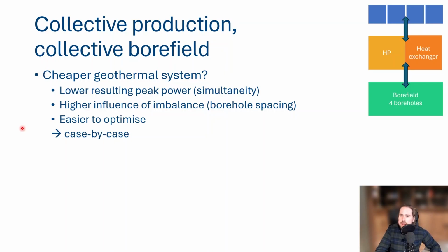Again, it depends case by case. For neighborhoods, probably not. And this depends quite a lot on the region you're in. But if you have a neighborhood, you basically are building a central district heating system. You have a central heat pump and your heat should be distributed to different uses in the neighborhood. And that's a very costly endeavor. It could be interesting, but probably not, with a question mark.